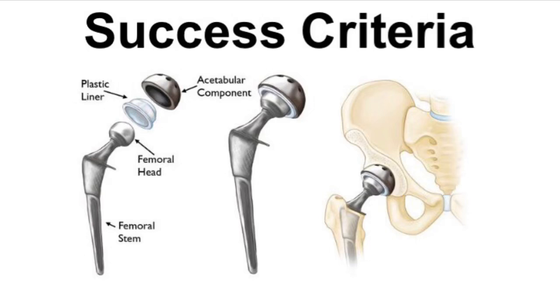To design a functional porous stem, we need to assess which kind of porous structure provides the best results, i.e., in the stress and strain of the bone, similar to healthy people, and the stem is strong enough to bear loading. This is all done throughout biomechanical analysis. The loading which I'll be using is 2000 newtons, due to the weight of an average human person.